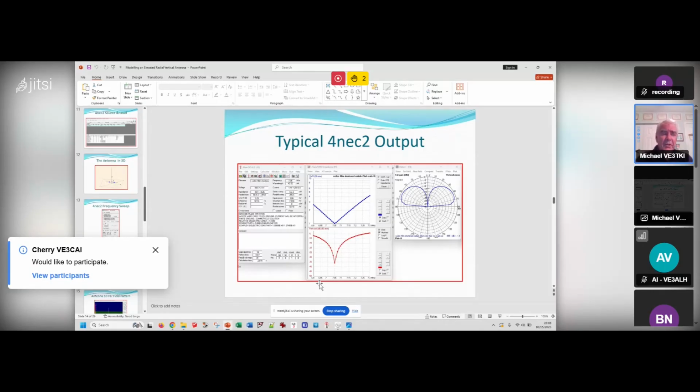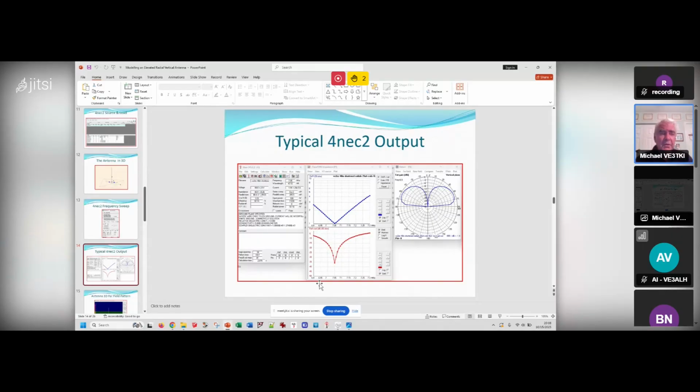Then I found, we talked to Ed, what you do is you take the quarter wave vertical, which is 39 feet. But what you can do is go say 29 feet, or 20 feet up your mast with a number 14 wire, and then use a 450 ohm ladder line to get the rest of the length.